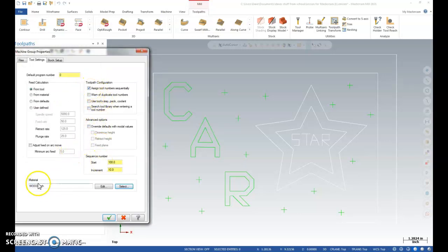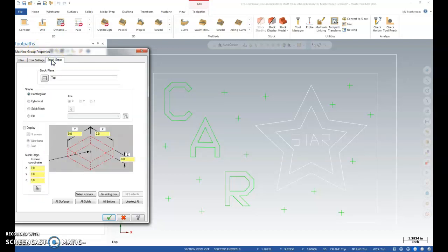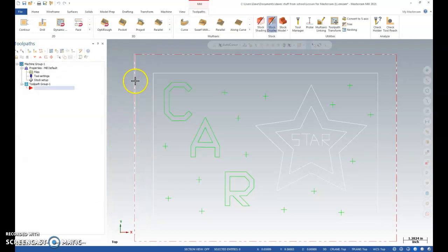Did that. Did that. Now I'm going to go to Stock Setup, and I'm going to say to display the stock setup. I'm also going to take 000, which is indicated as the center of the plaque right now. I'm going to move it here to this corner, lower left, as where all your drawings should be. And then next I'm going to put in the size of the plaque. So 10 for Y, 10 inches, 14 inches for X, and 1 inch for Z. Perfect. And I'm going to checkbox that, and you'll notice a red line around your guy.